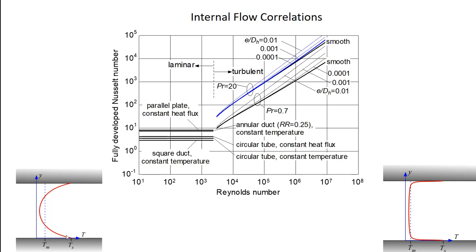It dictates how sharp or shallow the temperature gradient is. It's also not that surprising that the boundary condition matters, because again, it takes a little bit of time for the duct to react, right? You have to conduct energy all the way to the center in order for it to react to things that happen downstream, okay? So those are the things that matter for a laminar flow.